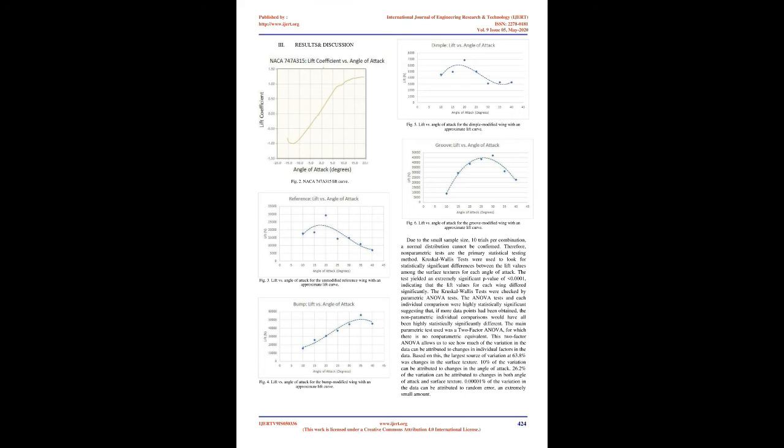Prior validation models place the range of error relative to real-world conditions with these flow conditions at less than 5%, lending credibility to the data. The four wings were tested at angles of attack from 10 degrees to 40 degrees in intervals of 5 degrees with the previously mentioned test conditions. Due to the unsteady nature of the solutions obtained from the differential equations, the final data contained 10 replicates of each trial. This ensured that the data used for analysis was not simply the result of a false convergence or other errors. As stall angle was the primary focus of this investigation, lift values were the only measurement recorded.